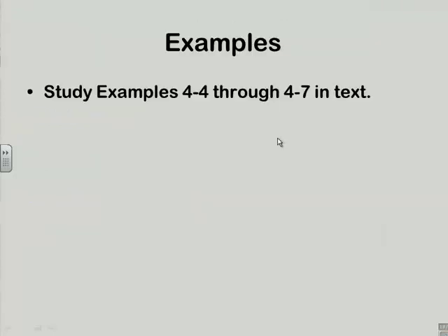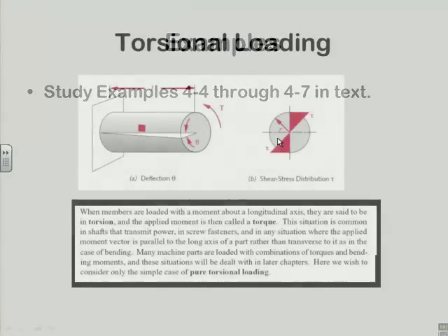So as I said, examples 4.4 through 4.7 do those examples of those 4 flavors of beam completely with no left out steps. And you really need to put your nose into those until you understand what's going on and how to manipulate these funny functions called singularity functions. The actual computation of them is made very simple by coding up that pseudocode that I just showed you.